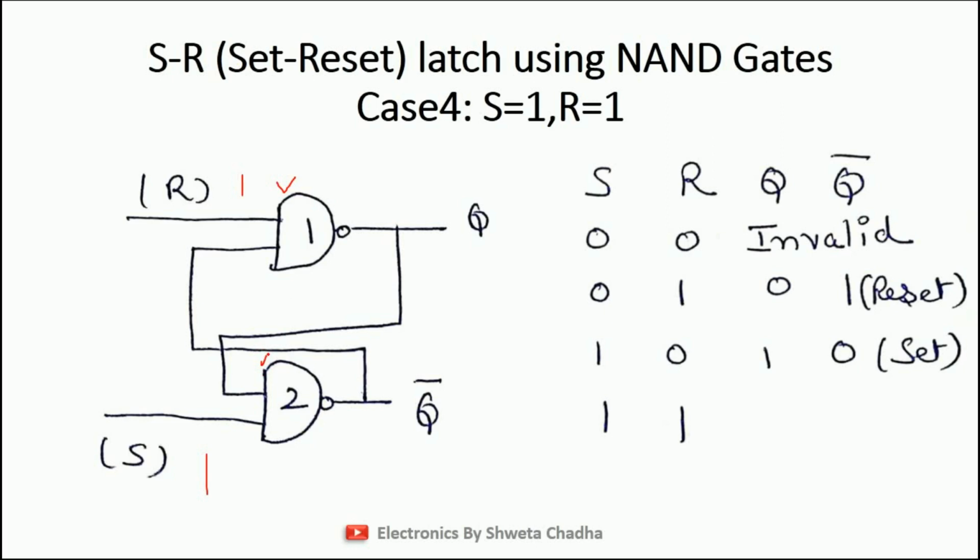So in such conditions where we are unable to simplify any of the gates, the solution is assumption. This is known as assumption because we are unable to start the simplification for both the gates. So we are going to talk about the assumptions now. So what assumption can we take? Obviously we can assume what was my previous output, and I can only assume 2 cases.